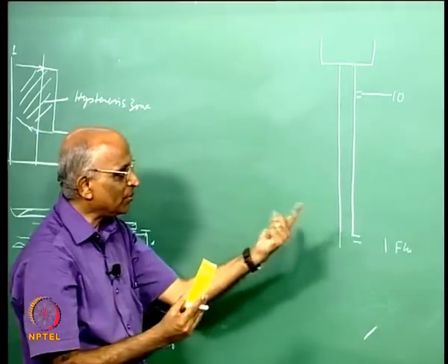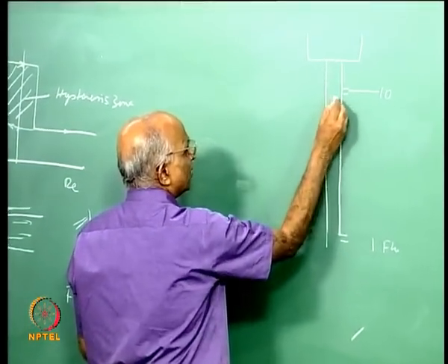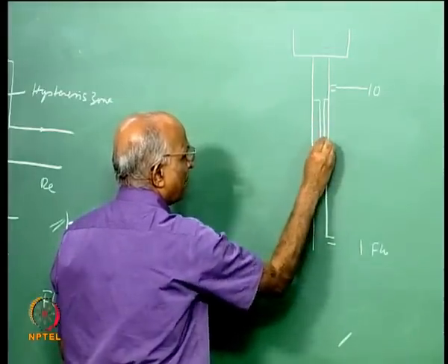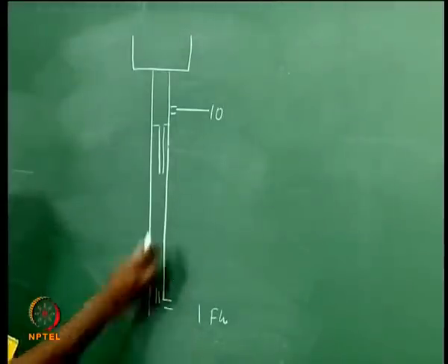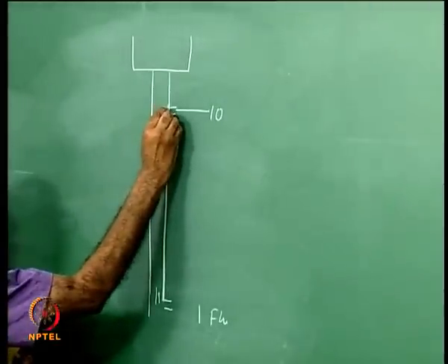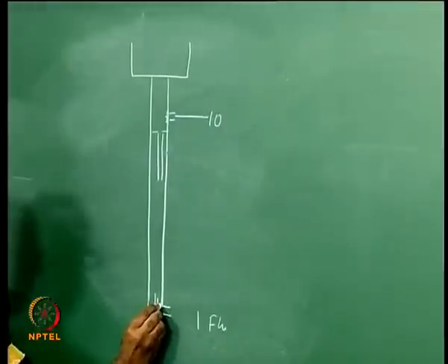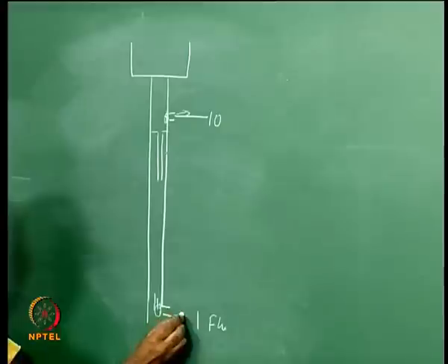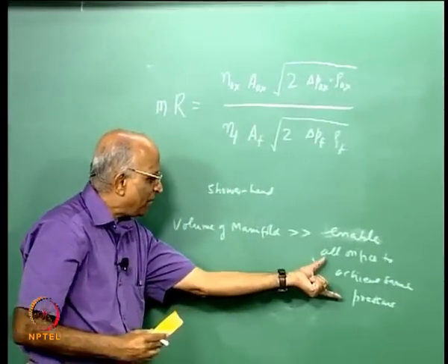And this is the same thing we use in our manifolds. See, maybe if I size this in such a way that I increase this, then I decrease this, then again I decrease this, such that by the time it comes here it has more resistance, then maybe the supply pressure could be the same. This is one. Or else I could put some filter here, or use a large hole filter here, something like a small filter such that I introduce some pressure drop here such that my supply pressure is the same. And so also in rocket injectors, whenever I have a manifold,